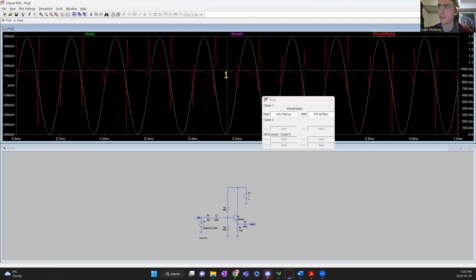So I feel pretty confident this is good because our biggest voltage discrepancy between input and output is going to be at these peaks here. And if I put it right at the peak where there's a gap, it might be slightly concerning if you're not sure it's more than 10% attenuation. I can just look at our gain equation and find out that it's still only about 4% attenuation. So I feel pretty good about that, and I think I'm ready to move on to the physical circuit.